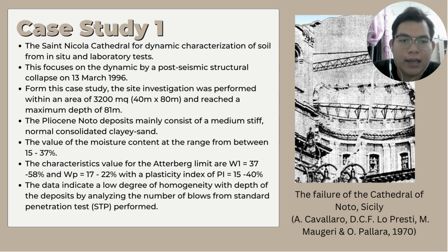The case study that I chose is about the failure of the Cathedral of Notre Dame, Sicily, the Saint Nicholas Cathedral, looking at dynamic characteristics of the soil from in situ and laboratory tests. This focuses on the dynamic behavior behind the post-seismic structural collapse on 30 March 1996. From this case study, the site investigation was performed within an area of 3,200 square meters, 40 meters by 80 meters, and reached a maximum depth of 81 meters.